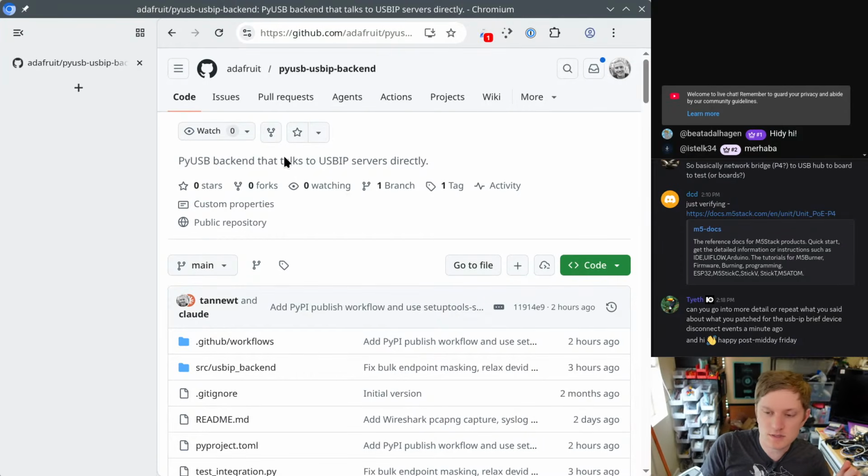And that's important because USB devices, when they come onto the network, have a default address of 0, and that means it needs enumeration, and the root hub has to tell it what address to use. So what was happening for me was that I was doing requests to this device, and I was managing to tickle it so it disappeared.